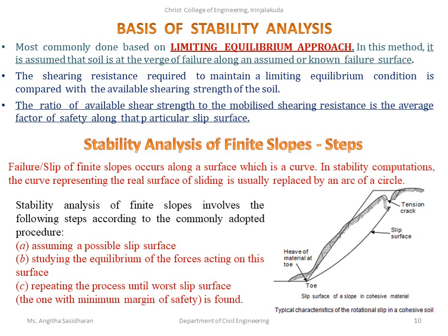So how much is the stress developed? That means that much resistance is offered to the deformation, to prevent the deformation. So the material has some strength, and some of it is being used every time to offer resistance, which is induced as stresses. So what do you mean by mobilized shear strength or mobilized shearing resistance?